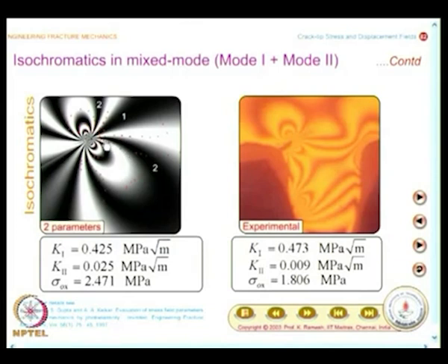And you have the data collected from your experiment, and this data is utilized to find out the coefficients in a non-linear least square sense. Please make a sketch of this, and you should also make a reasonable sketch of the experimentally observed fringe pattern. Actually, this feature is because you have a stress raiser here, that is why the fringes here are distorted.